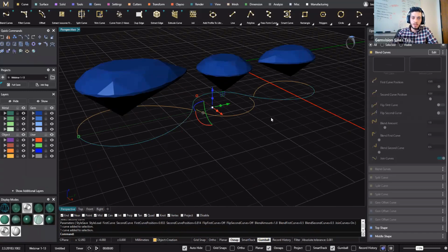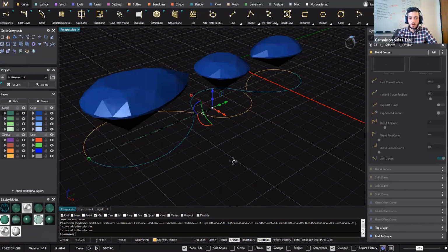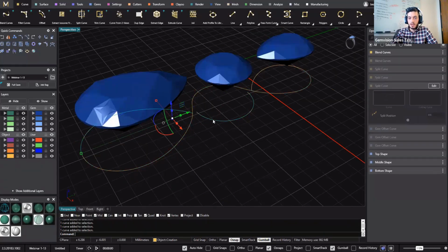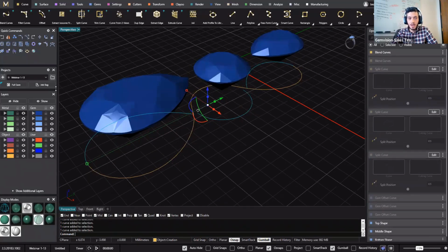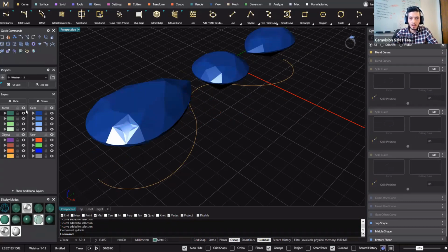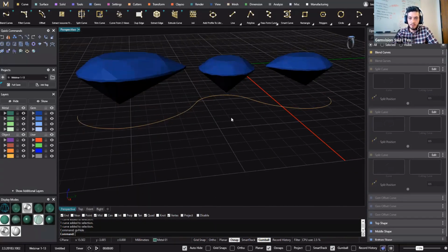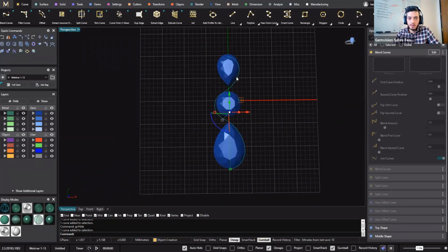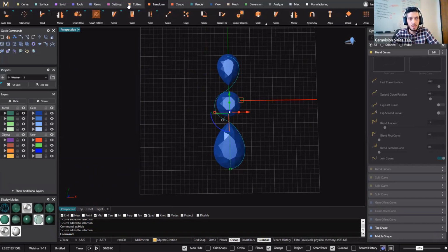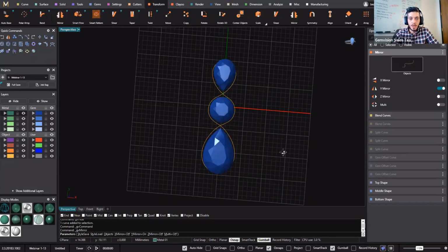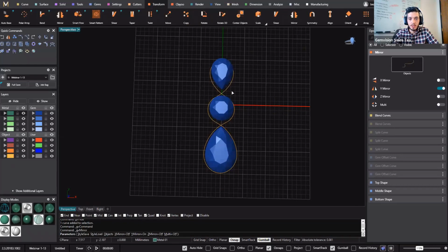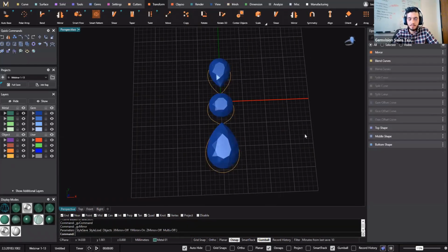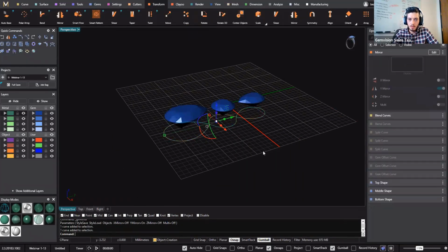So there's a few ways that we can move forward right here. I don't necessarily need this side, right? Because I can type GV hide and make them disappear. I can select this curve and mirror because it's the exact same thing that I am needing, right? So let's go to top view. Under transform, I have mirror. And when I hit mirror, you can see it completes my curve, right? Now I have 2.